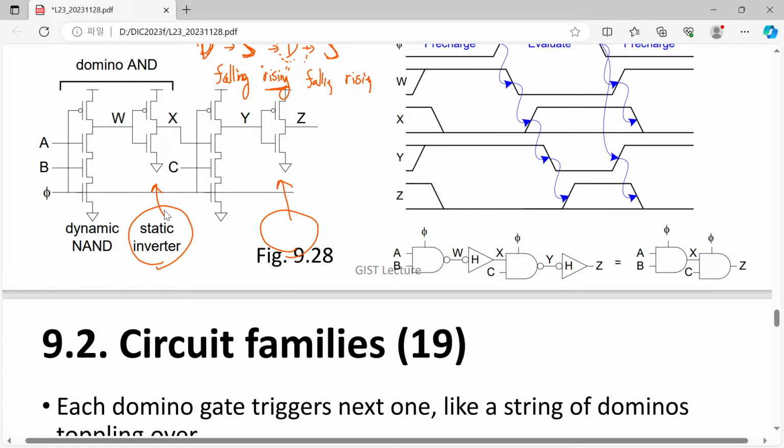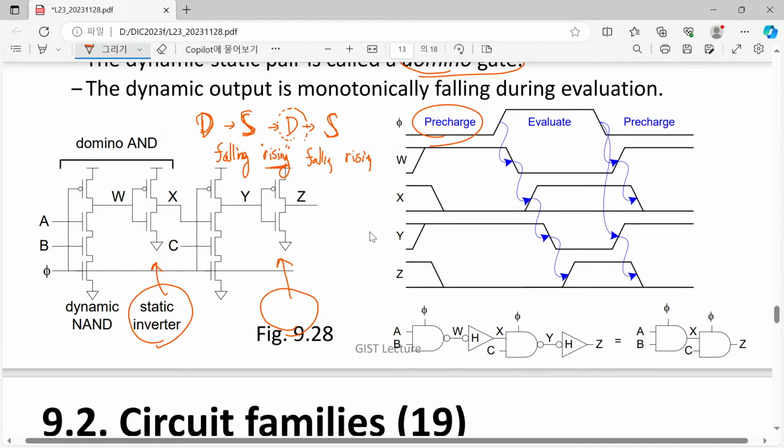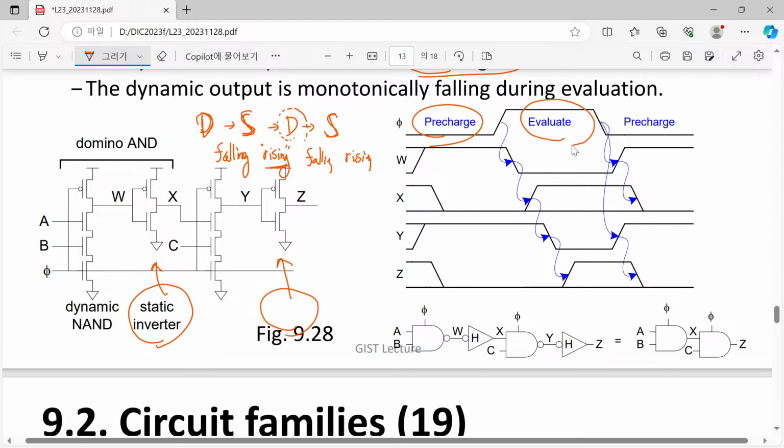That can be analyzed as this pre-charge phase. Once all of the setting is over, then what happens? The very first domino brick is just touched. After that, the signal propagates all over the logic gates. That is quite similar to this evaluation phase.